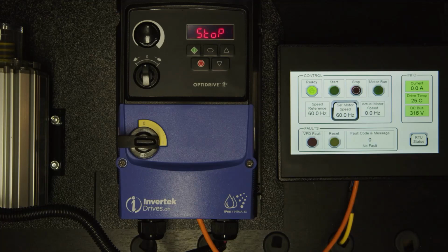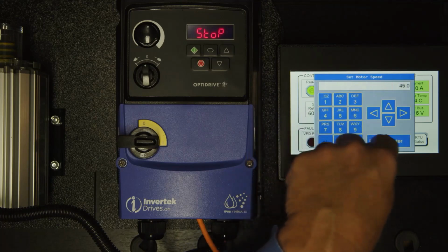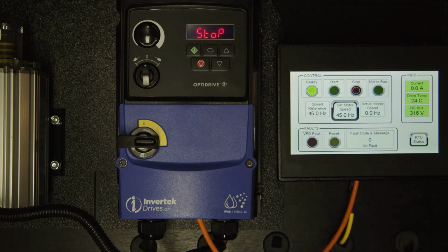Once we stop the motor, run feedback will also be set to 0. If we change our motor speed reference, or the motor speed that we want to set to, our speed reference goes down to 45 again. The next time the drive starts, if that speed doesn't change again, then our motor will run up to 45 Hz. In this particular example, the acceleration times will be set in the drive itself. So this is our VFD bench setup.